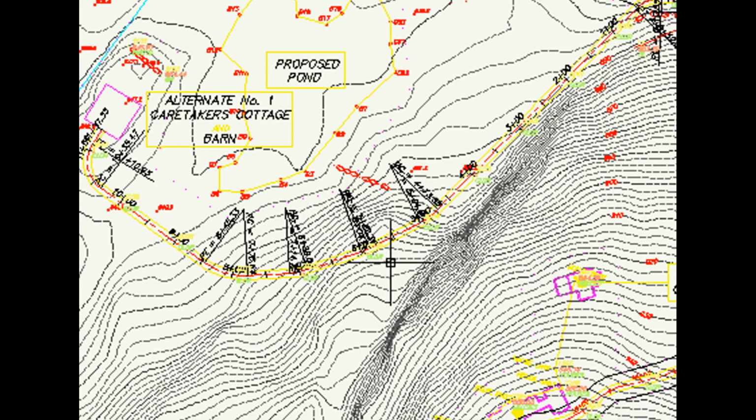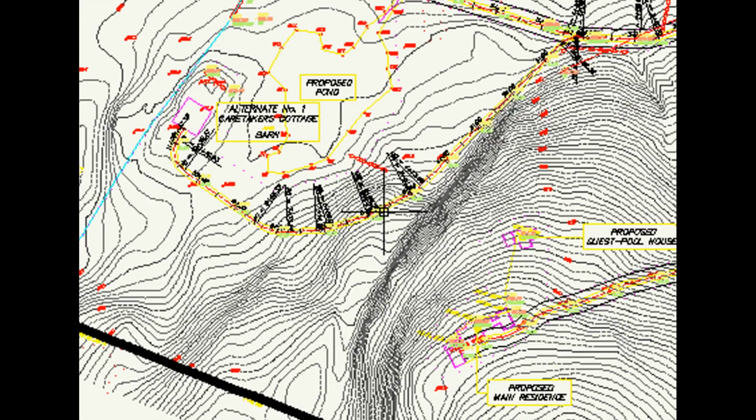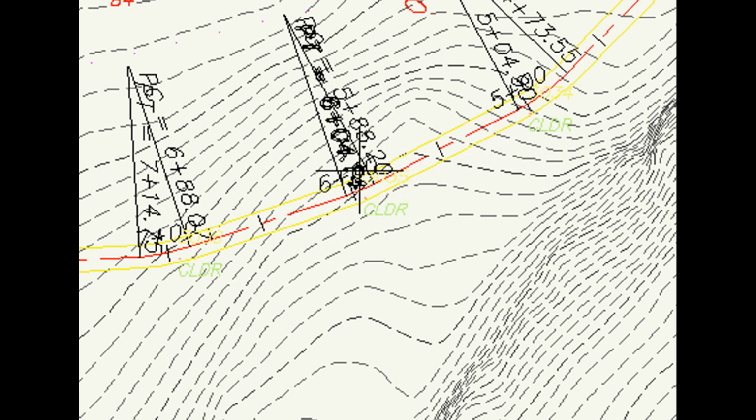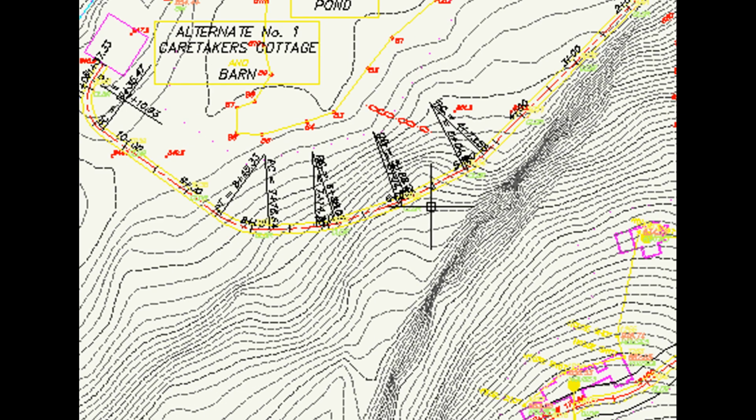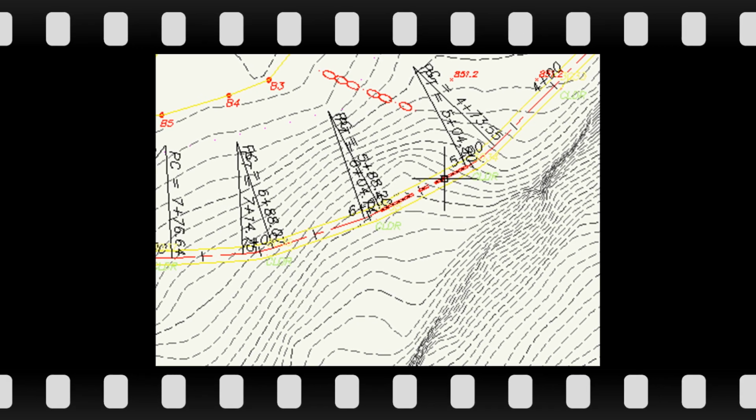So the spot that you're looking at is right here. This rock ridge sticks out, and this is a driveway coming up to the main house from the main drive. They had to cut through this ridge, and the excavators were going to take forever with rock hammers to do that. So we chose to use explosives. You basically drill holes to the depth of what they want to cut, or a little deeper, and then they pour it full of ammonium nitrate. This is particularly 1.1D explosives. You can look into that further if you like. And they blow the ridge, and the big rubber mats you see the excavator moving are blasting mats. Those go over top of the rock after they lay charges, before they blow their charges. It basically protects people and equipment from flying material. A lot of energy coming out.